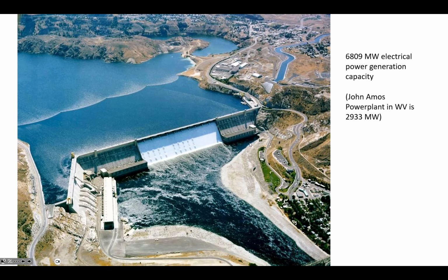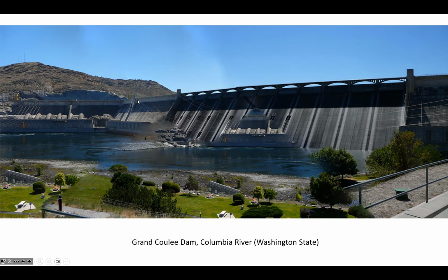So at the Grand Coulee Dam, most of the time water isn't flowing over the top of the dam, because if you do that, you're not capturing any electricity from it. You can only get hydropower when the water is flowing through an enclosed conduit and then comes in contact with the impellers of a turbine. And so ordinarily most of the water is going through what are called penstocks, which are large diameter pipes that carry water from the dam and then down to the receiving river.